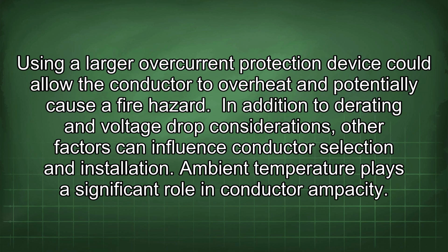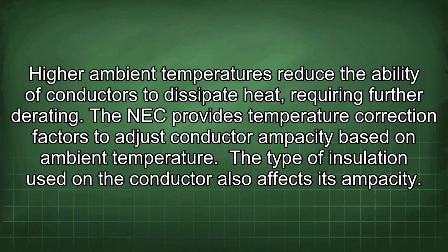In addition to derating and voltage drop considerations, other factors can influence conductor selection and installation. Ambient temperature plays a significant role in conductor ampacity. Higher ambient temperatures reduce the ability of conductors to dissipate heat, requiring further derating. The NEC provides temperature correction factors to adjust conductor ampacity based on ambient temperature.